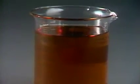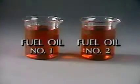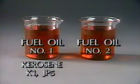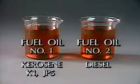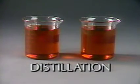How does it burn? And what must you know about fuel oil to install, adjust, and service a fuel oil burner successfully? First of all, fuel oil for heating comes in several grades. In the number 1 oil types, there are kerosene, K1, and JP5. JP5 is a type of jet fuel that is sometimes used as fuel oil. Number 2 fuel oil is usually supplied in one grade. It's also the diesel used in powerboats, trucks, and automobiles. Both 1 and 2 are made during distillation at an oil refinery, and each has slightly different characteristics which make big differences in the way they produce heat.